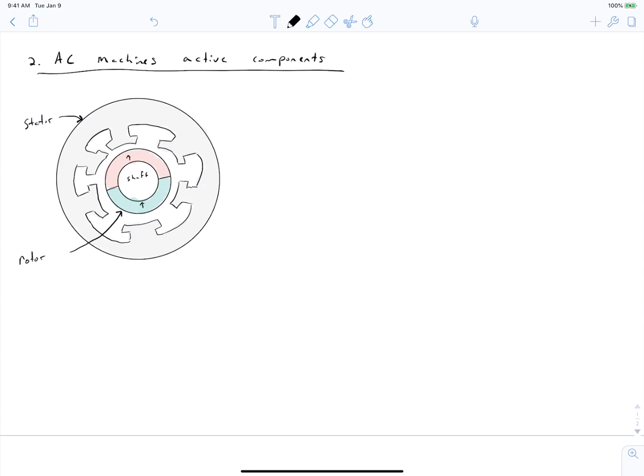So what is not drawn on here are any of the components that are not used for active electromechanical energy conversion. All of these components are strictly magnetic components, that is, they carry the magnetic field, and they are used in the process of converting electric energy to mechanical torque. And we're now going to break down the stator and the rotor separately in a series of diagrams. But remember that the complete motor system also includes the bearings, the frame, more details on the shaft and the coupling. But in this class, our focus is on the electromagnetic design.